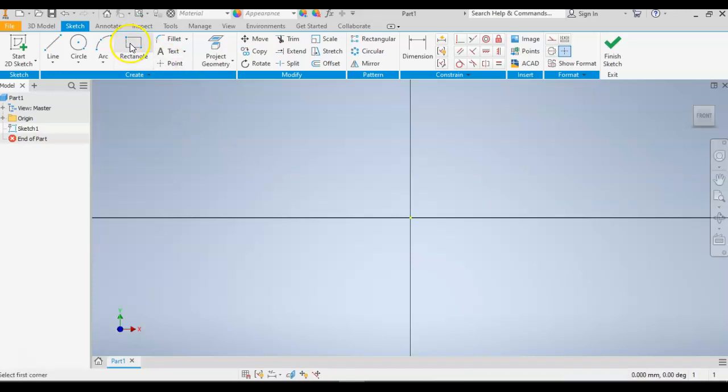Click on the rectangle tool. And with that rectangle tool, you're going to go to the plus sign or the very center called the origin, and you're going to click to start when you have a green circle. Always try to go to the positive section of the coordinate system as you're working. And now we're going to head to the keyboard.